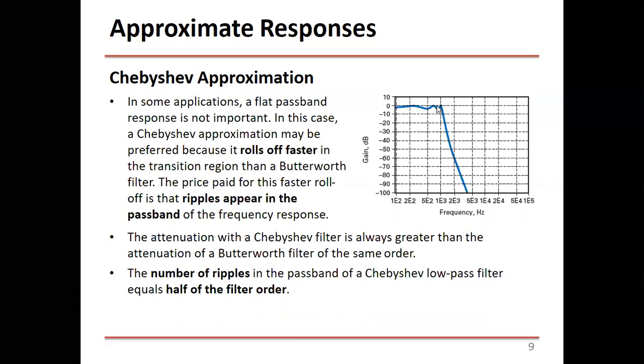So this is the main advantage. You sacrifice a little bit with some error here. Like the gain here is not uniform. You accept some attenuation, a little bit, but it's very small. You can go from 0 to minus 0.9 or something, or like minus 0.1 or something. And on the other hand, by doing this, you gain the sharper transition roll-off.